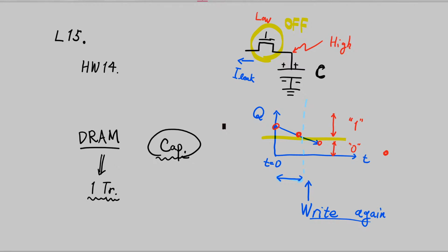So after this procedure, what will happen to your DRAM? Then your DRAM bit becomes once again stronger. Of course, in this case you have to write it again, and again it will move down, and after the same time period it is written again, and again. So now you can easily understand that in the case of DRAM you have to quite frequently check the status of your DRAM cell and also write it again and again.